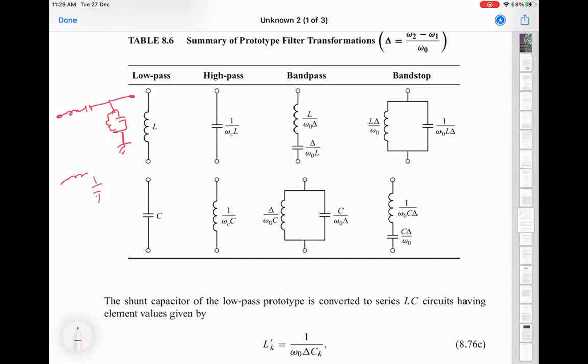And it's obvious to see that if these two LC circuits had the same resonant frequency, then at that resonant frequency, the series LC circuit has zero impedance and the parallel LC has infinite impedance. So that is equivalent to saying that this point is essentially connected to this point and this doesn't play a role. So you can see it will have maximum transmission at the special frequency corresponding to these LC circuits. And if you go on either side, you will get only less response. Right? It can only go down. So this tells you again just intuitively why this is a band pass filter.